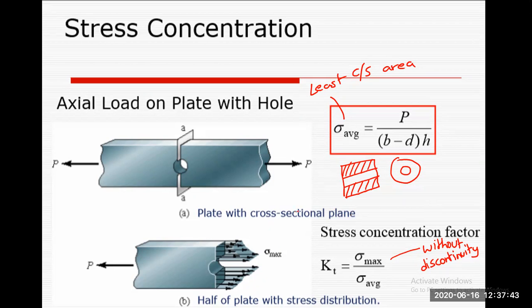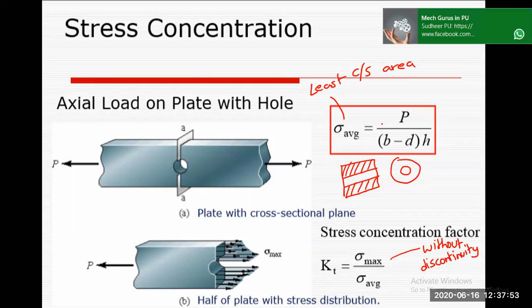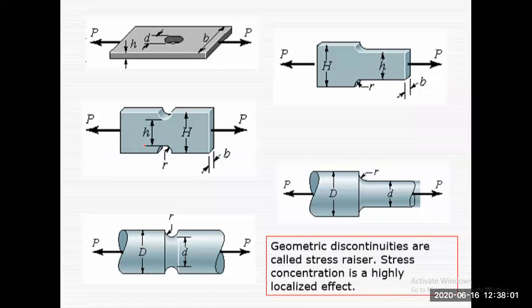Okay, so that's how it works. You consider the stress concentration factor whenever there is any discontinuity in the part. So this is not true only for a plate with a hole. There are many such cases in which there are discontinuities. Without discontinuities, there can be no machine part, so therefore you have to have this discontinuity.